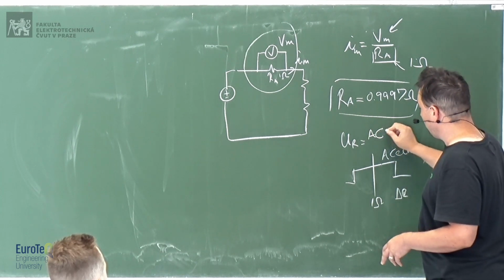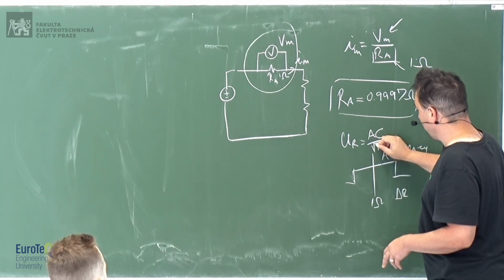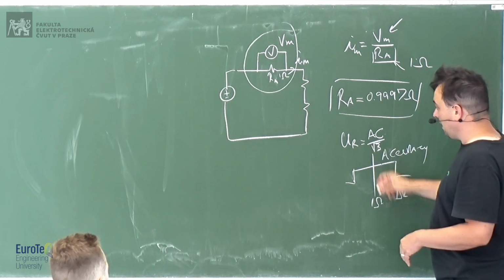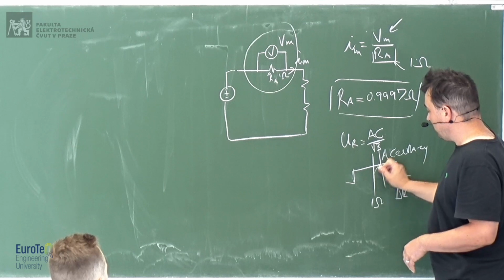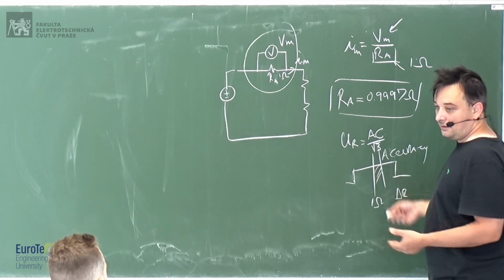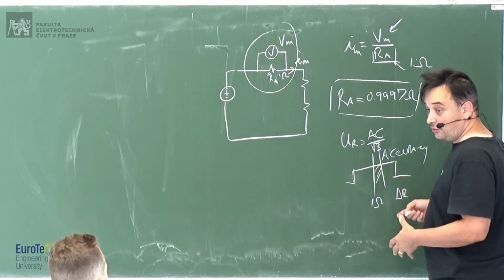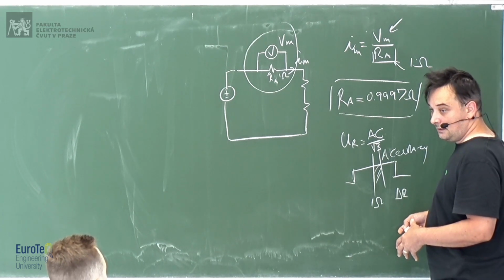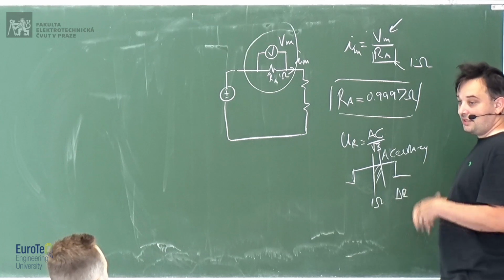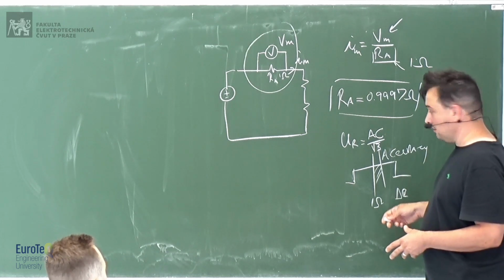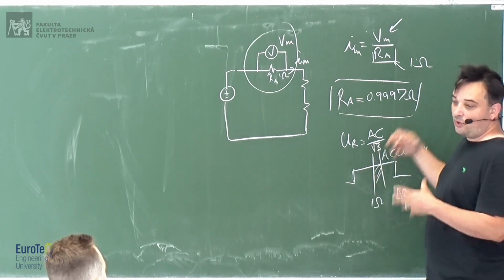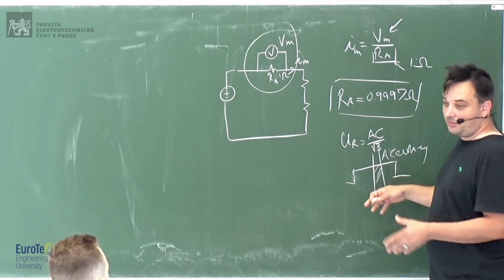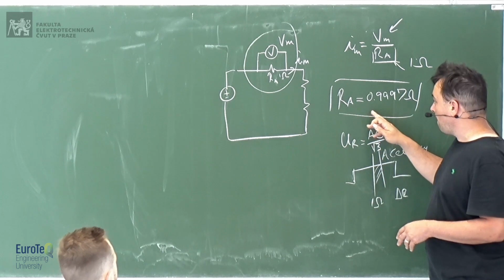You take your accuracy, you divide it by square root of 3, because you assume uniform distribution, and you get one standard deviation of the distribution of the resistance. Okay? And the accuracy is that tolerance that they've given? Yeah, so 1%, 2%. For instance, if you have 1 ohm, it's very simple because it's 1 on 1%, 1 divided by square root of 3, blah, blah, blah. Okay? Fine.